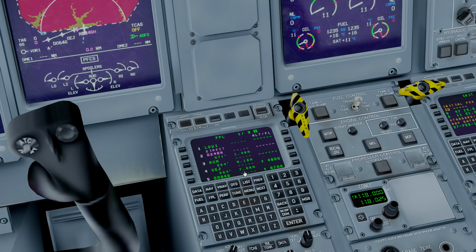Now what's different, especially for me when I first tried this aircraft from a Boeing perspective, is there's no need to enter any specific altitudes or speeds. There may be some restrictions at different waypoints, just like they would appear on the standard instrument departure chart. But other than that, there are no real restrictions or calculated flight paths.